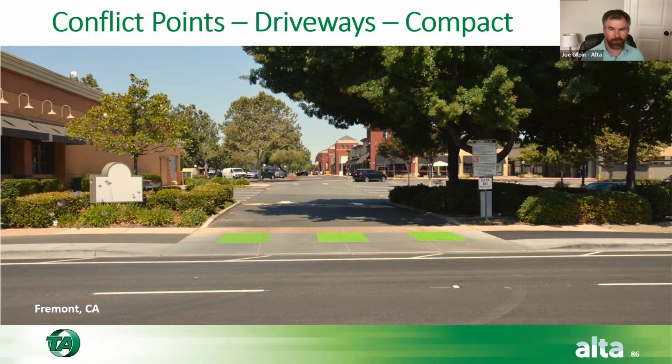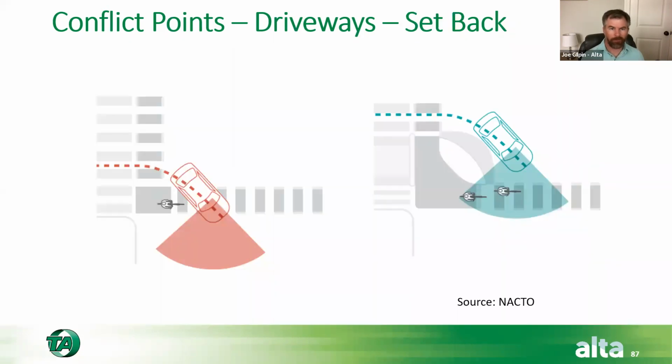The next thing that we can do is pull the bikeway back, try to bend it out, separate it a bit more, and increase the lateral separation between the bike lane and the driver. And this is a graphic that comes from a guide that NACTO put out about 4 years ago called Don't Give Up at the Intersection. And the principle here is that when you have a bike lane immediately adjacent to a vehicle, and we'll talk about this more when we get into intersections, you tend to have the bicyclist be in kind of the blind spot of the car. And that's why you'll see dashed out bike lanes and class 2s out there, because the idea is that you want the vehicle to get in the bike lane so that people are single file ahead of that conflict. And I'll come back to that in a little bit.